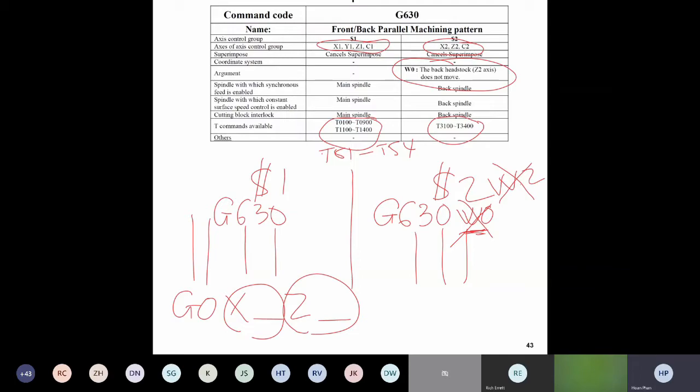For example, in the last mode you can use G600 mode, and then you have a tool activated, say tool number 2. Even if you cancel it already, the tool still stays there. And as soon as you enter this G600 mode right here, it will use that tool to move to the position you command.